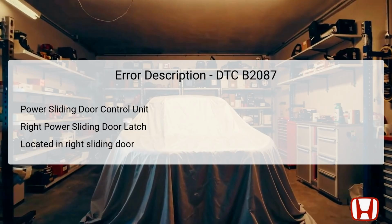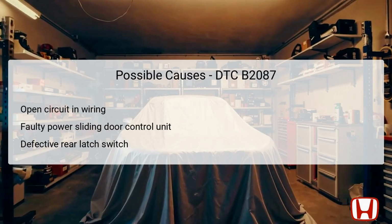Any fault within this circuit, such as an open condition, can directly impact the door's operational reliability, leading to inconvenience and safety concerns. There are several potential causes for the DTC B2087 error code. Firstly, an open circuit in the wiring is a common culprit, which may involve damaged, frayed, or disconnected wires, disrupting the electrical connection.